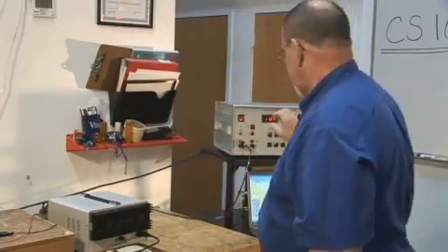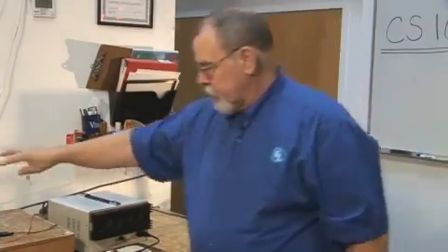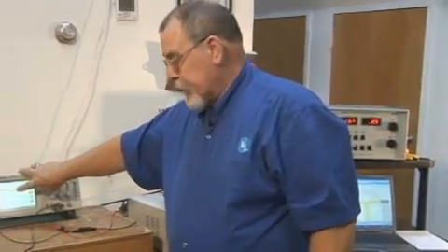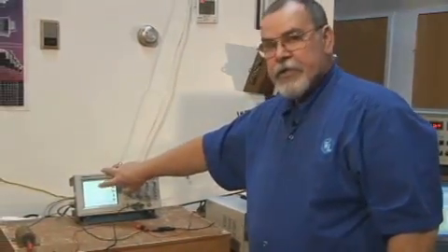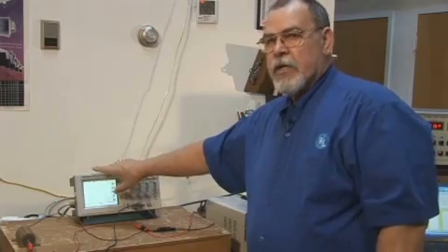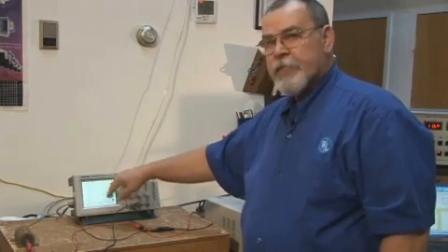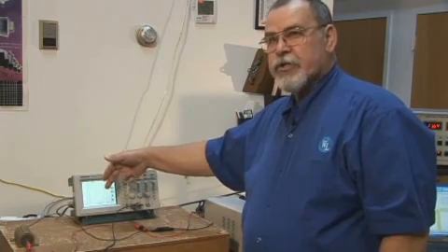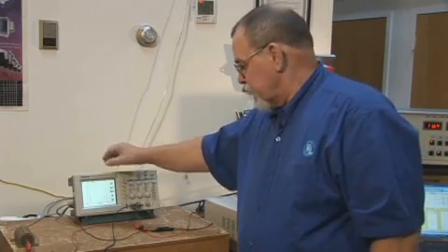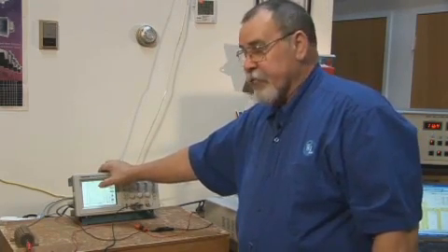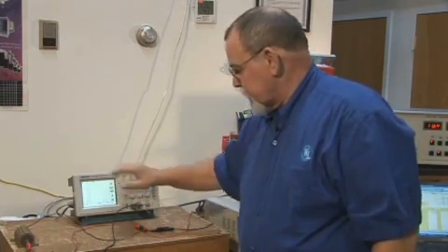The idea is I need to measure the interfering signal, the voltage being applied here in the presence of all these items. Now there are some oscilloscope filters available that will take 60 hertz out. It also removes some of the interfering signal, so it requires calibration. But for our purposes, we don't have it available, so we're just going to monitor this.